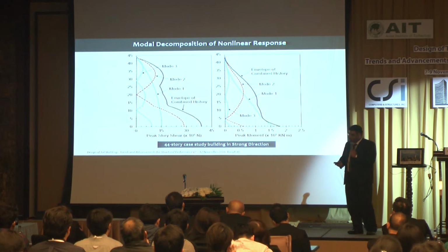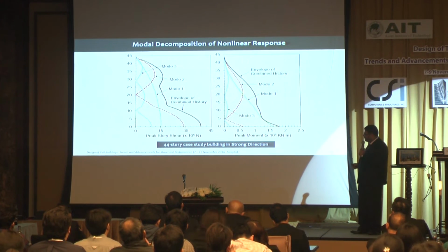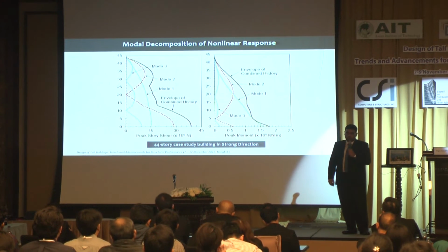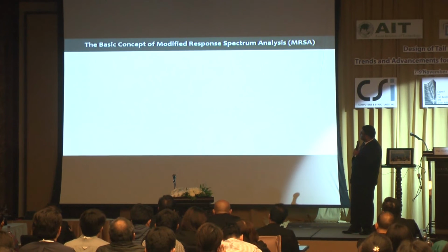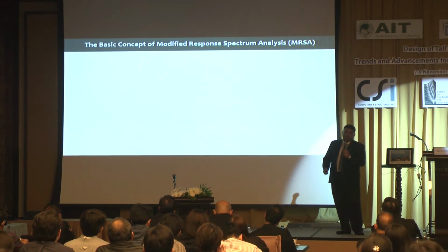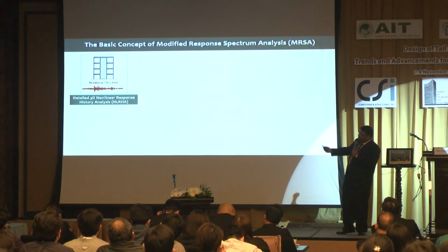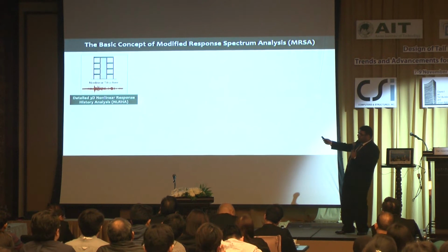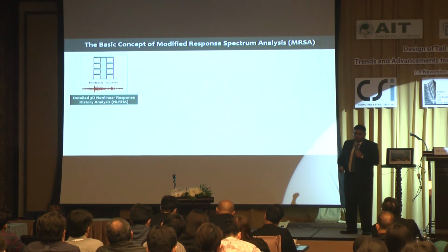But researchers have shown that this coupling effect for lower levels of nonlinearity can be ignored, but this has this assumption as well. So, knowing that this modal separation idea is working, the complex response of a nonlinear single degree of freedom system, a nonlinear multiple degree of freedom system, can be seen as a few nonlinear single degree of freedom systems.